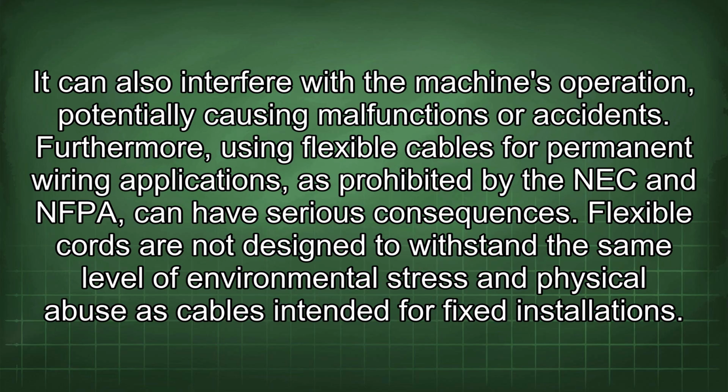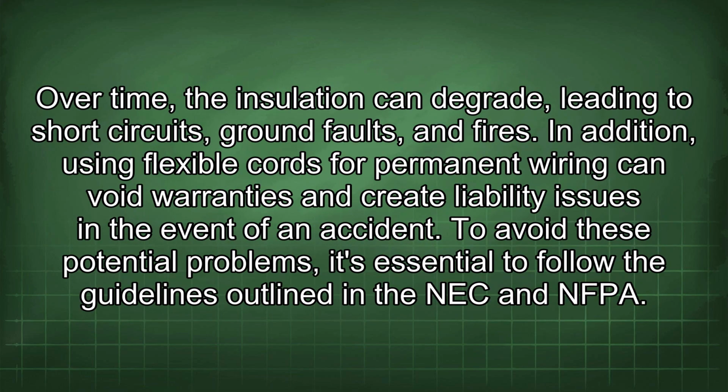Furthermore, using flexible cables for permanent wiring applications, as prohibited by the NEC and NFPA, can have serious consequences. Flexible cords are not designed to withstand the same level of environmental stress and physical abuse as cables intended for fixed installations. Over time, the insulation can degrade, leading to short circuits, ground faults, and fires. In addition, using flexible cords for permanent wiring can void warranties and create liability issues in the event of an accident.